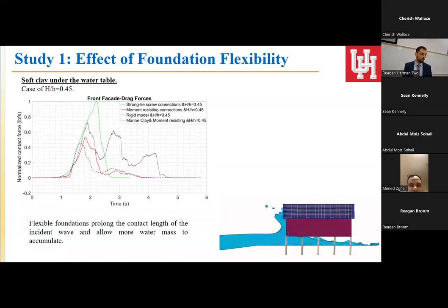Another very interesting thing is that one could oversimplify this and say it looks like a cantilever beam, or a reverse pendulum, where you have the mass on top and just the support on the bottom. So there is a semi-sloshing phenomenon happening here. That's why we get the consequent peaks, which are very different from all the other cases without soil structure interaction. This is mainly because, to be honest, this pile embedment depth is relatively low. You won't find 5 diameters in practice right now, but it was still interesting to study.